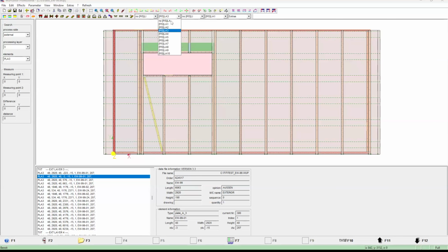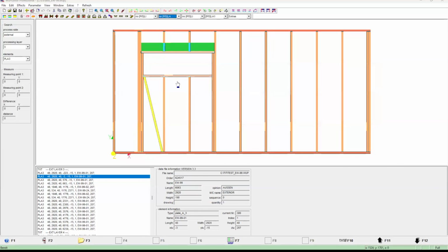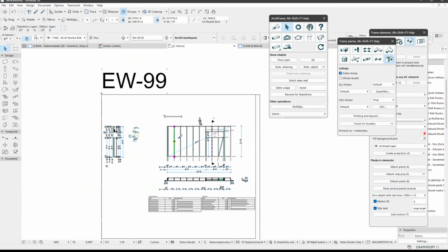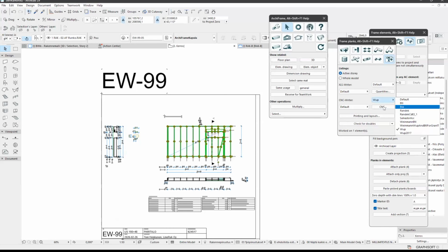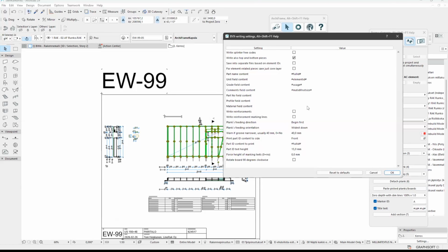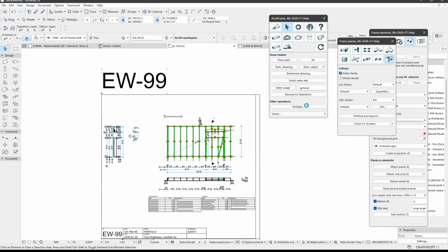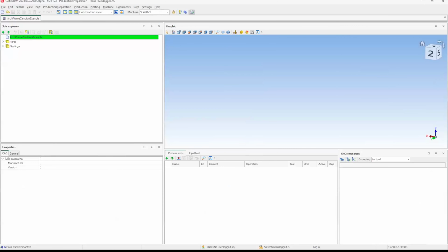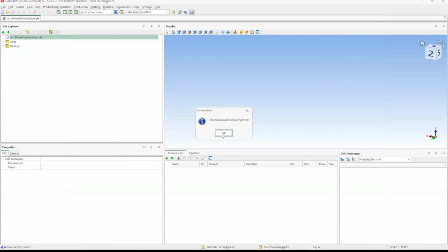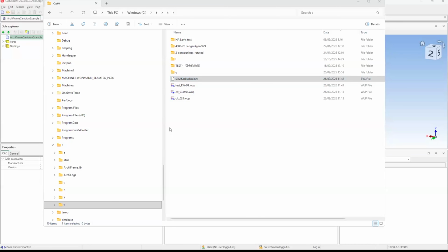And then we have the main framing here. For the cuts, if I save only the main framing in Hundegger BVX format, saving the CNC is something like a save-as operation. Let's go with these settings. I open the Hundegger software and take the file and drop it here. Maybe that wasn't completed. Let's see if it's still thinking.